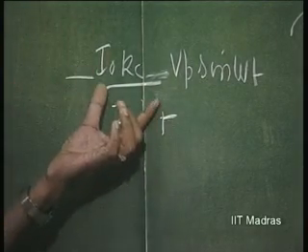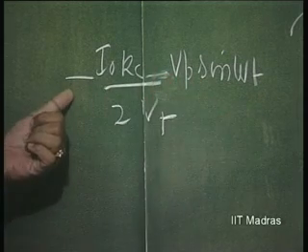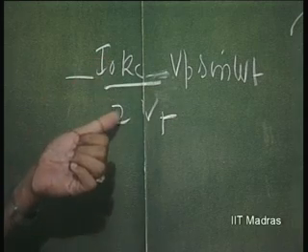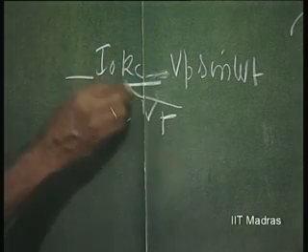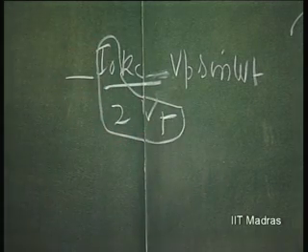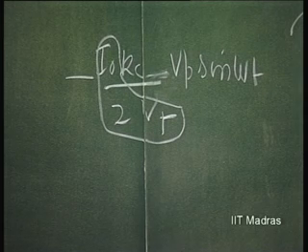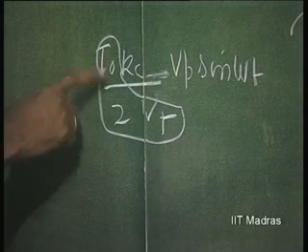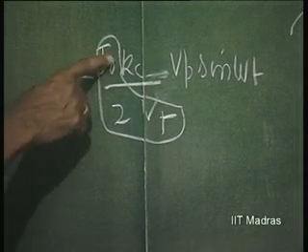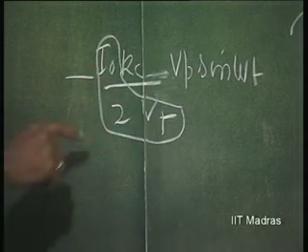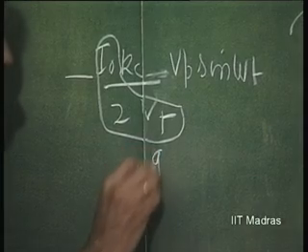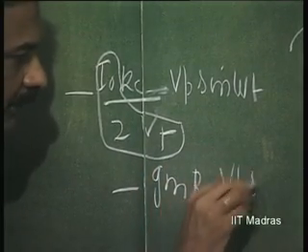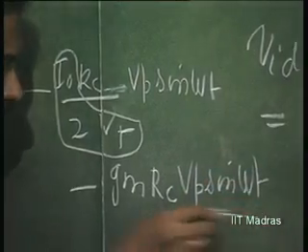This is the gain, this was the original signal, and there is a phase inversion. This whole thing is nothing but Gm of the differential amplifier, Gm into Rc. Each transistor is operating at I naught by 2, and therefore, that I divided by Vt is the Gm, that is Gm into Rc. So, this is Gm into Rc minus Gm into Rc into Vp sin omega t. This is actually the wanted input.